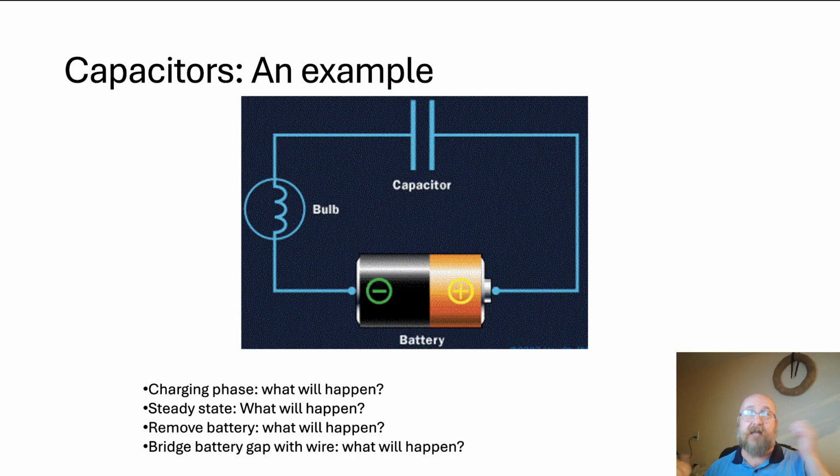So just like what we saw in the earlier simple diagram with the pluses and minuses, during the charging phase, there will appear to be current flow because the electrons are flowing through the light bulb to the negative side of the capacitor, and they're pushing electrons off of the other plate of the capacitor and going around down below. This means that the light will come on while it's charging, but once it reaches full charge, all current will stop and the light will go out.